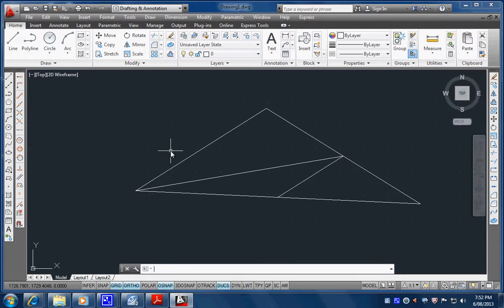That's not how you type it. Try again. Line. So that comes up and enter. It doesn't know when I finish typing anything, so always enter. That's one of the important golden rules to remember. When you type anything on the keyboard in CAD, you've got to press enter. A lot of people make the mistake of not reading what it's asking them. That's telling me specify first point. So I've got to read what it says. Sometimes it doesn't make much sense, but at least it's better than nothing.